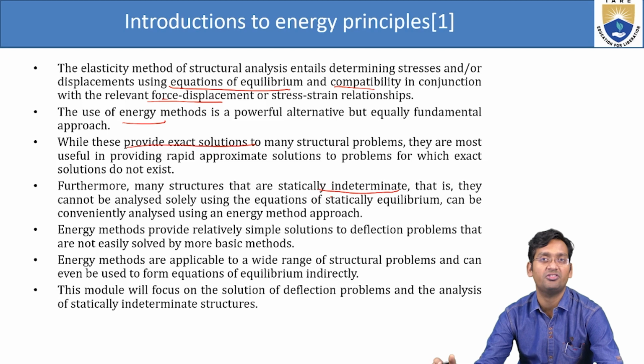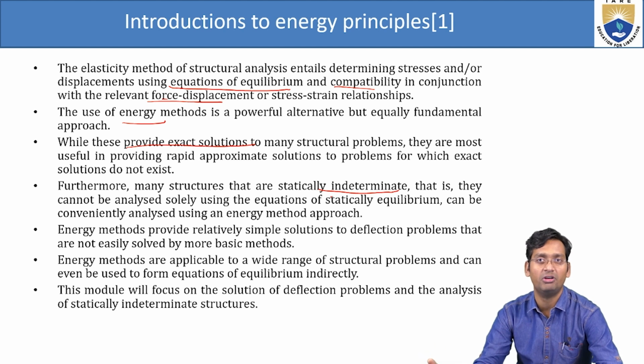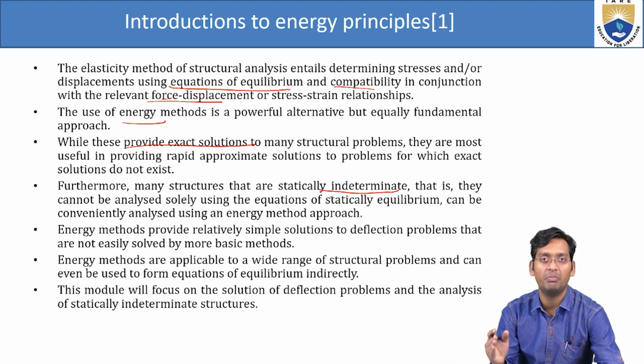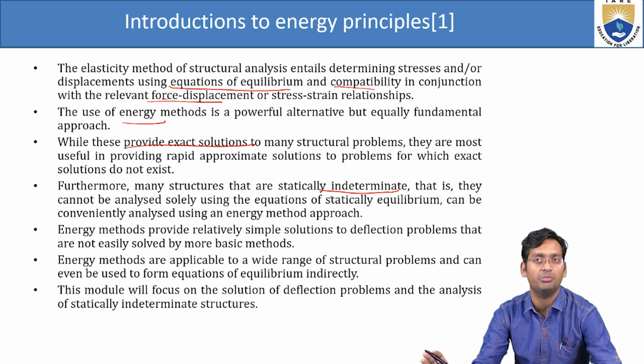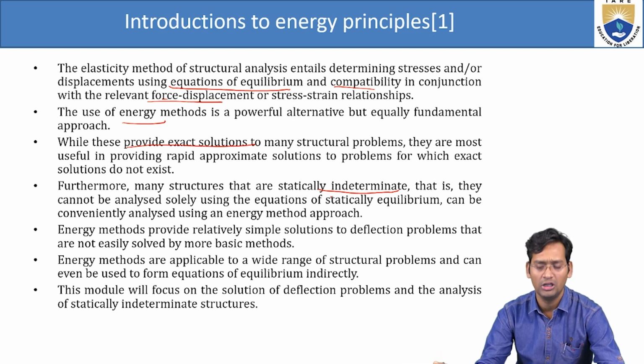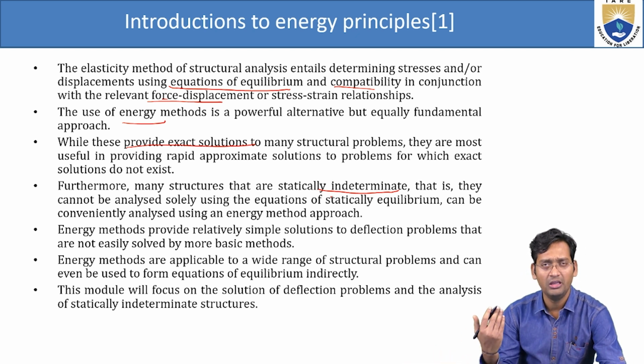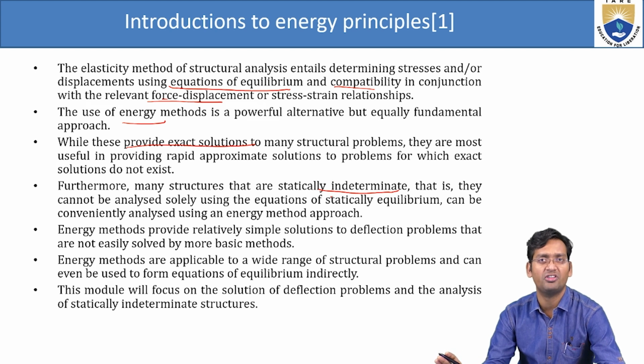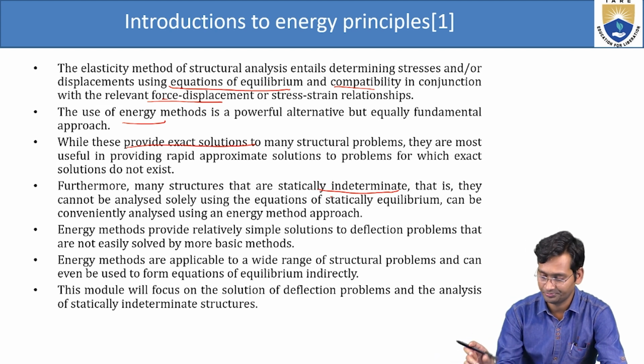Suppose some indeterminate structure is there whose solution is not available, then we go with the flexibility method, in which we remove members till the structure becomes determinate. Now that it is determinate, we can find the solution. So by using the energy method, any type of structural problem we can solve.